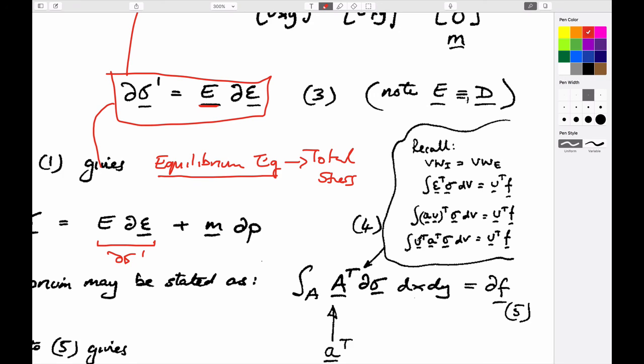If we then define what strain is, we know that strain in terms of finite element equations is equal to our A matrix multiplied by nodal displacements. That's just one of our deformations. These are the derivatives of the shape functions, you remember, right? And so if we substitute for this here, we have this.